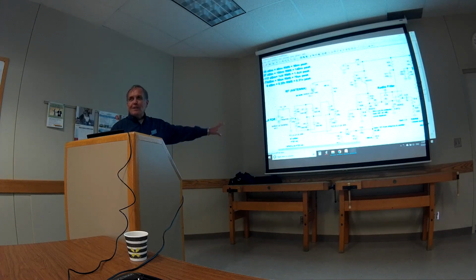This has lots of notes in it, and you do it by just going up to Edit, and you can put notes in there. I like to do that so when you go back to the model, you can see what you've had before, what kind of voltages you found, without having to run it all and start from scratch again. Typically, coming in the antenna, I just put some typical values for signals that you see coming into an antenna.